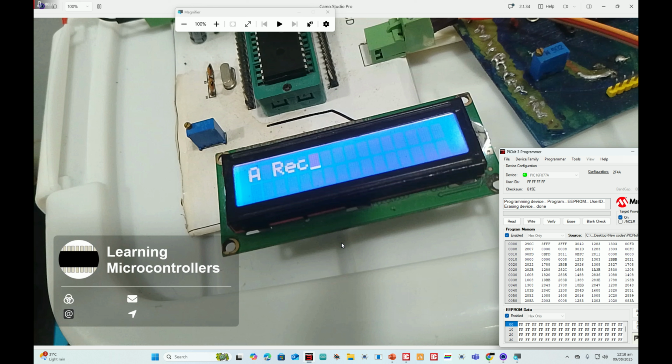So this is basically just a demonstration of UART communication. You can use loops as well, like you keep on sending one character 2000 times to make sure that it's sent for 2 seconds, or you can use a timer or an interrupt as well. So this is how you use these commands to play with an LCD, to establish a UART communication and to display data on the LCD.